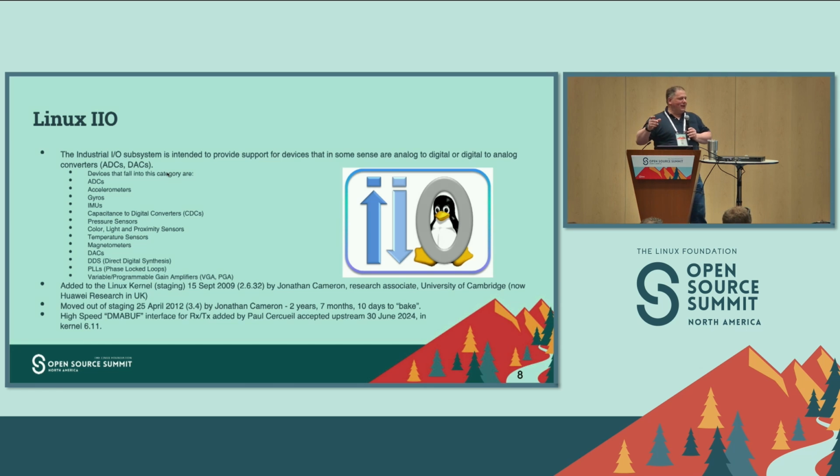Devices got put in miscellaneous, they got put in hwmon, they got put in human interface, so there was a big mishmash of different places, and the person who wrote the device driver did the application, so it was very combined. IIO tries to separate those things and make them a standard format so you can access things in a standard environment, specifically from a sensor standpoint.